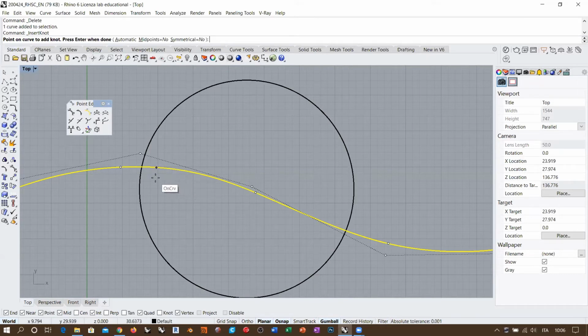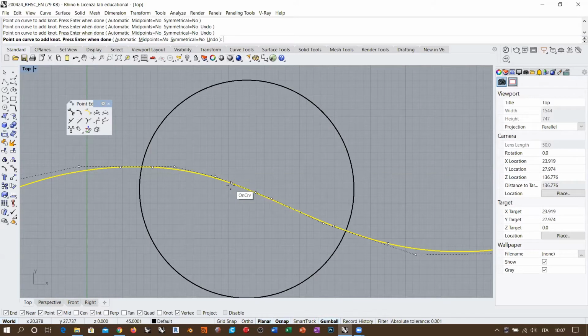So what I'm going to do, I'm going to place an initial knot here, a final knot here, and so I know that inside I have 2 spans already. But I need local deformation, so I need 1 span in this area. And you see that we still have a knot here. So I need to create, for example, a knot here. And you see that in this case, the control points are becoming denser in this area.